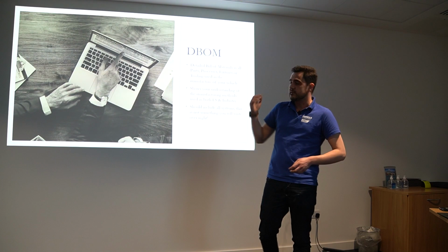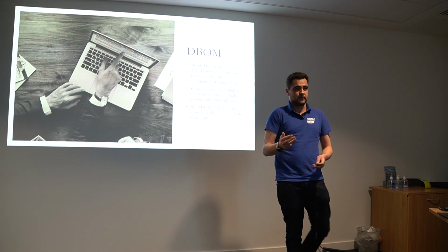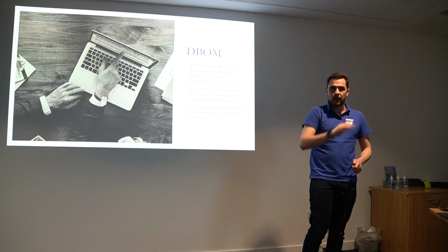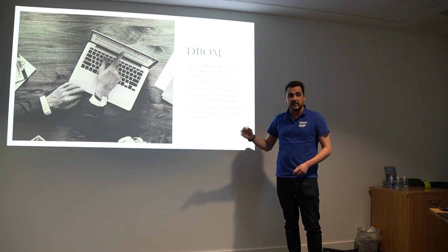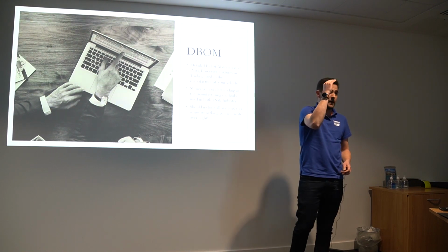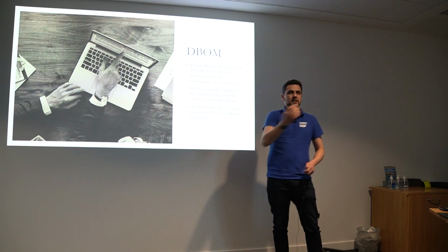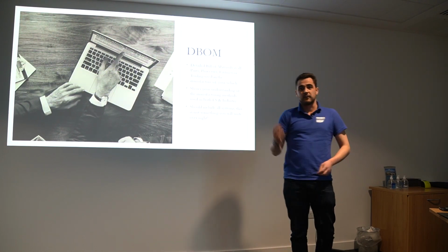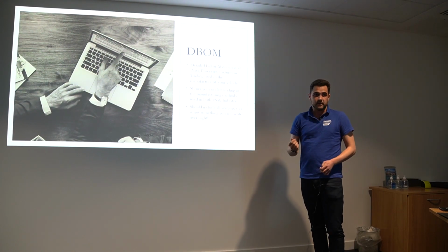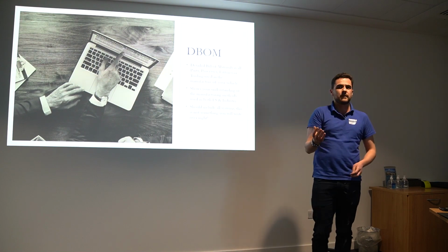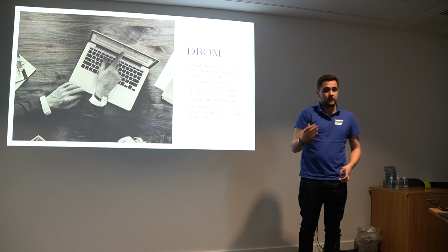So a detailed bill of materials is every process, material, fastener or tooling used within your vehicle. Everything. We want to see the whole lot. The idea is we want to test your manufacturing understanding. At this point, you're not adding the costs in. This is just to show us that you know how to take a piece of billet all the way through to a part that you've assembled onto the car, or laminates, or whatever it is you're using for your vehicle. We want to know that you know that process. So this should include all of the systems. The detailed bill of materials is broken up into 8 sections, so all of those should be in play.